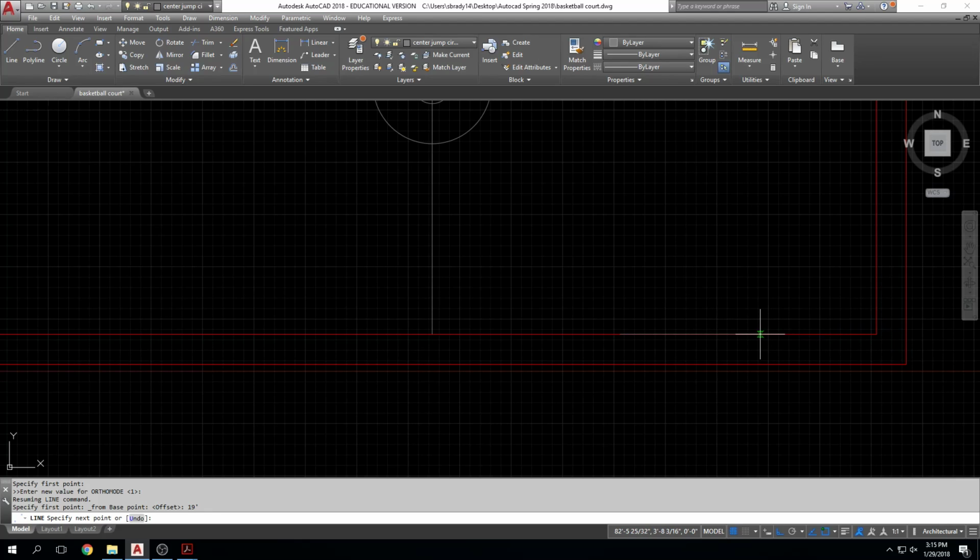Because I have a nearest snap that was along that line, but it didn't keep that second point right on there. But the second that I initiated a snap, even though I didn't click on that snap, and even though this line wasn't going all the way there, that somehow kept it a little bit straighter, right? So now I can type 3 feet, 36 inches and get that little line right there. Okay, so maybe that's the answer to the question.